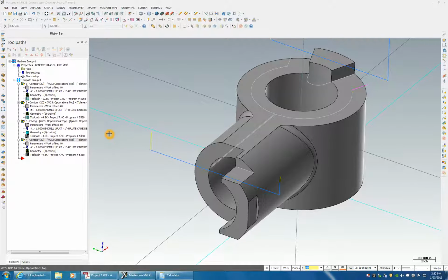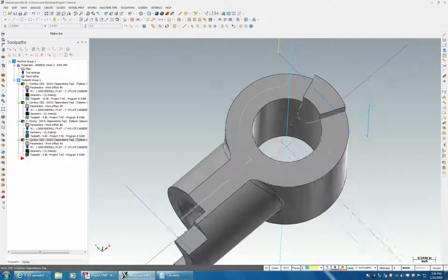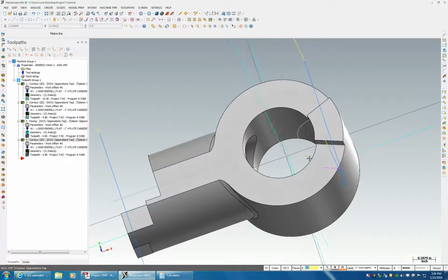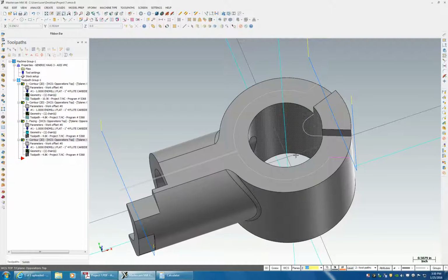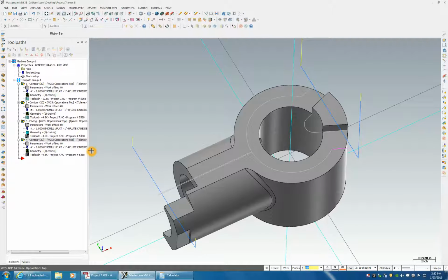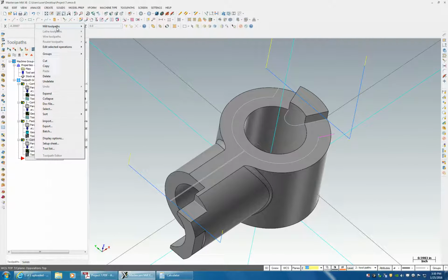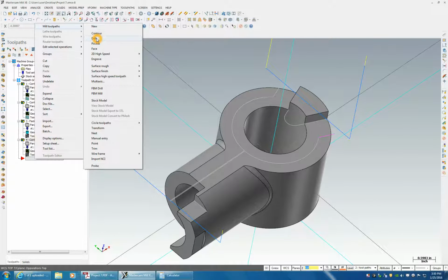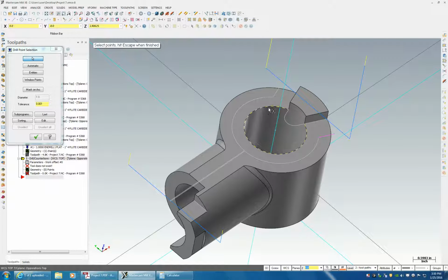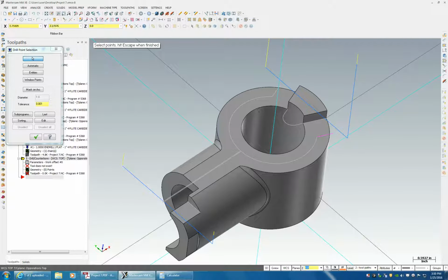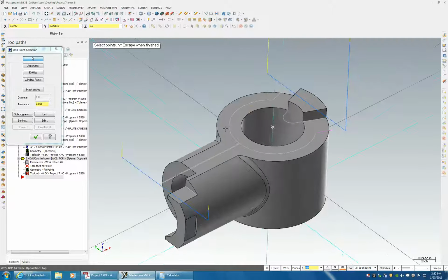We're going to assume that we have a reduced shank 1-inch cutter. Basically that our cutter, if we take this 1-inch cutter and we're going to mill down through here, that when it passes the flutes, it's not going to rub the wall. So let's just make that assumption in this particular part. So we're going to do a mill toolpath, and we're going to use a drill. And our drill point, we can use the center of this, is there.